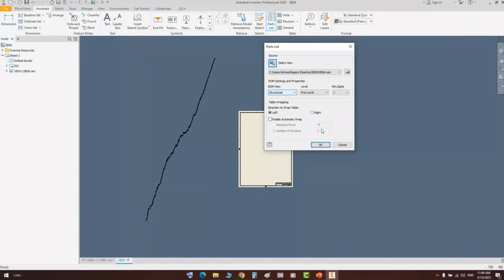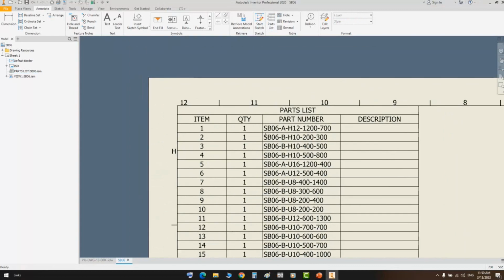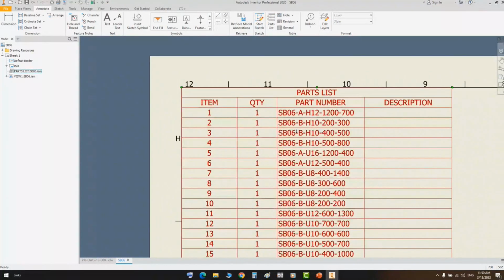In case of selecting the structure, here we will discuss the difference between structured and parts only. In version 2023, you will not find the structure legacy or part legacy. Those types, which are structured and parts only, will cover what we will talk about. So if we select structured, you can create a bill of material for the structure. Here you have the part name for each support. So the structure will give you the main assemblies only without the levels of detail.